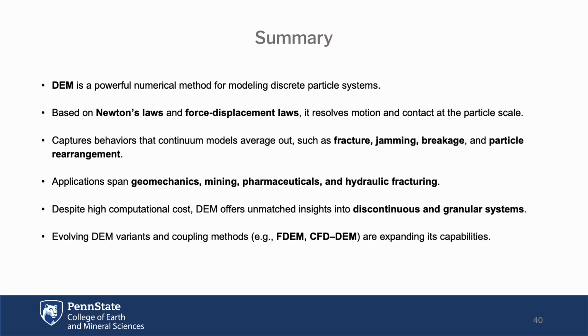In summary, the discrete element method is a numerical framework for simulating the physics of particle-based systems. It is grounded in Newtonian mechanics and incorporates realistic contact models to represent how particles collide, slide, and dissipate energy. Unlike continuum approaches, DEM excels at capturing localized discontinuities, making it invaluable for modeling complex phenomena such as fracture propagation, granular mixing, and particulate transport.